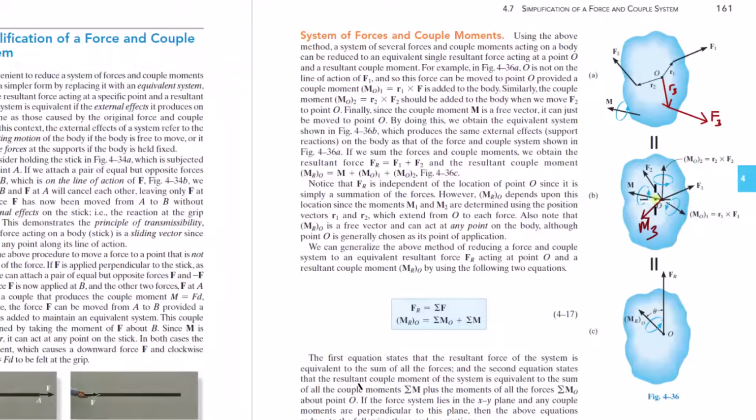Right? It's going to have a rotation. You don't have to put this rotation sense, but the rotation sense would be like that. But F3 is still here. Okay, so now this is just another moment vector at point O. Its tail is aligned with these other moment vectors. You could sum M01, M02, and M3 and get a resultant moment. Now this resultant moment, though, is not a free vector anymore because you've got this fixed vector mixed in with it.